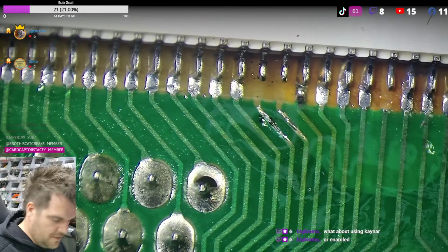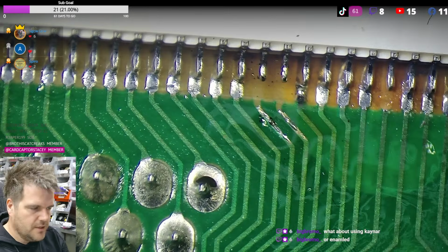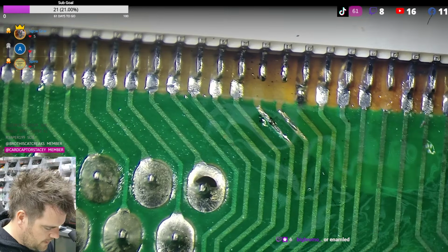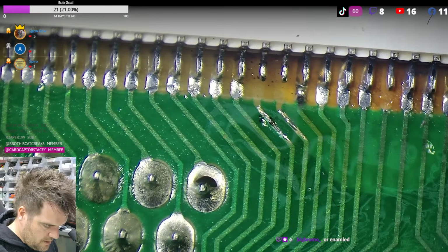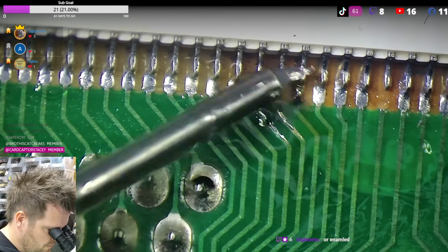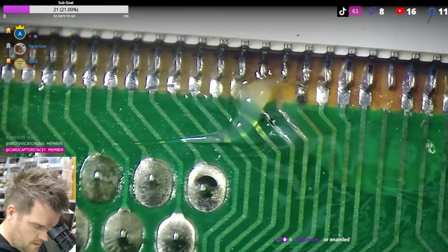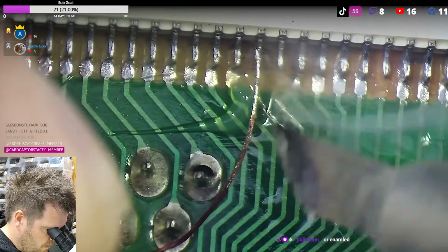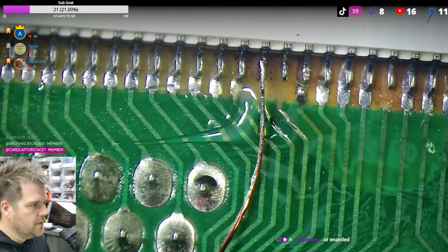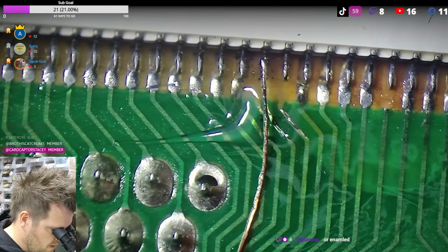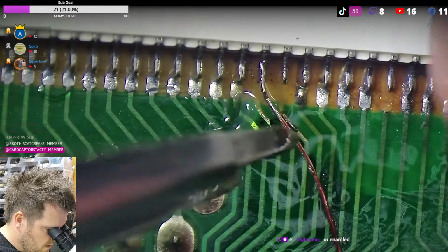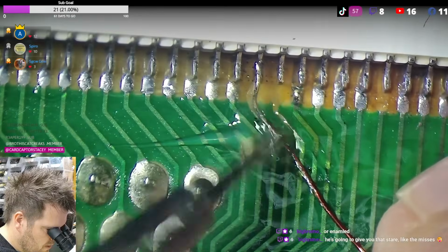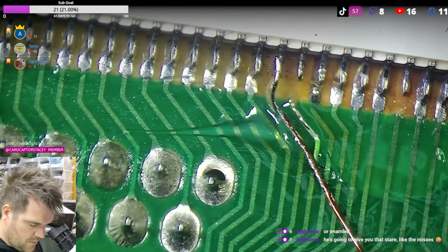Right, so let's get onto this. So I've got some normal enamelled wire. Do exactly the same as what we just did. Probably need a bit of fresh flux now. And then you can go onto the pin. That's better when you're used to working with it anyway. And then go down to here, bend it into position. And I haven't stripped that wire the best.